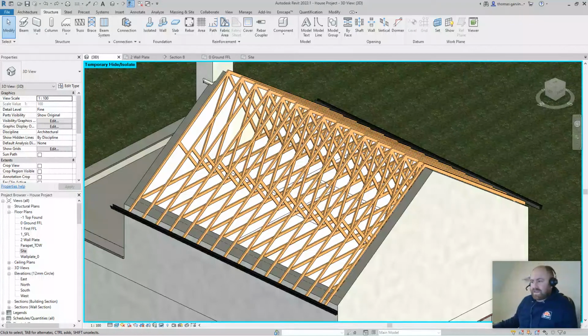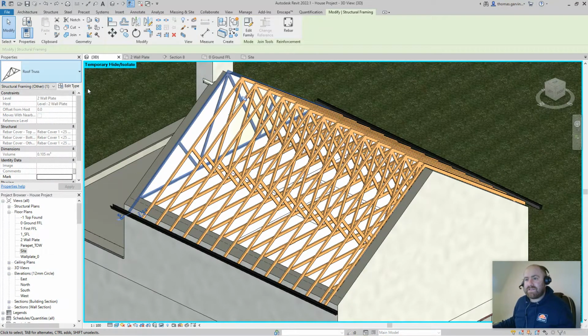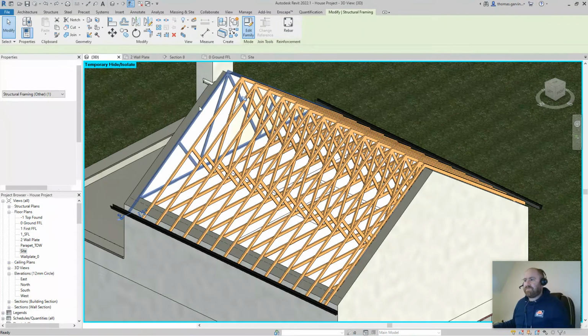Hi everyone, we're going to make a gable ladder and we're going to use the Revit Truss family. It's the out-of-the-box Revit Timber Truss family. And we're going to edit it and save it as a new family and take out the infill elements, the tie and the bracing. And then we load it outside the wall. Okay, so we select that truss and edit family.